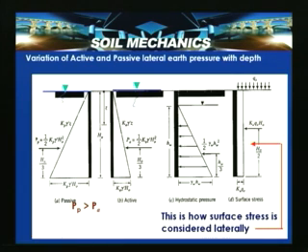Similarly, if that condition prevails here and the wall moves towards the fill, then this is the equation Kp gamma dash z for the pressure diagram, and Kp gamma dash h naught is the ordinate at the base. Then Pp is equal to half Kp gamma dash h naught square, the passive earth pressure thrust. Kp is greater than Ka, so the earth pressure thrust in the passive case is much more than in the active case.